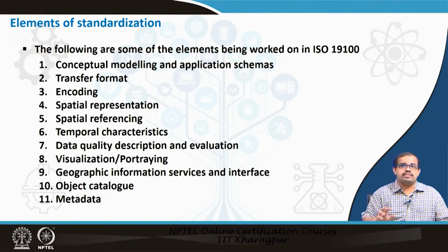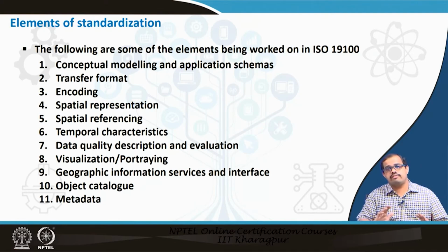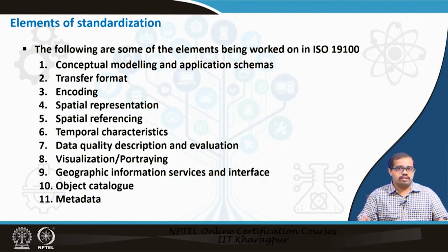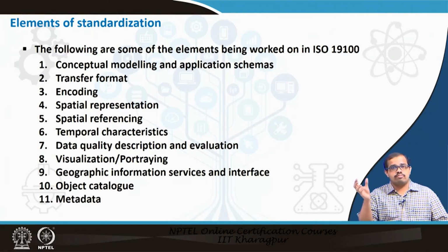It is not that every sensor will work all the time, or that it is extremely accurate. You have to evaluate a particular sensor, particular device, and look at what is the error mode. Only once you have understood the error mode, then you add that error to whatever readings it is providing. So, that error evaluation is extremely important. Whenever you are putting out your data, you have to mention what is the error that data has in itself. That also has to be mentioned, without which the standardization or maybe transferring of your data may not be possible at all.